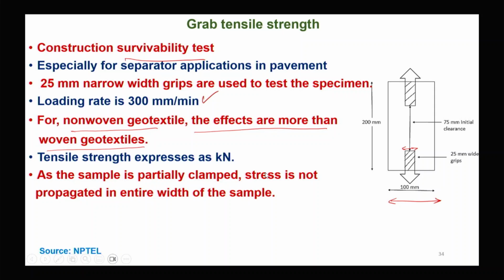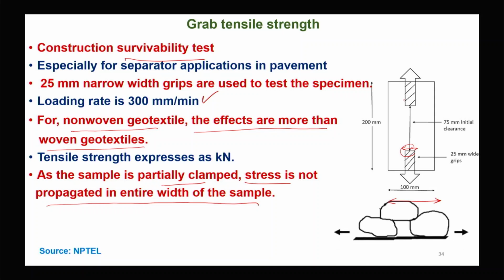Here the sample is partially grip clamped, so stress is not propagated on the entire width of the specimen, which simulates the actual application of geotextile during construction. Now let us see this condition. Here a geotextile is being placed, and over it the stones are placed.